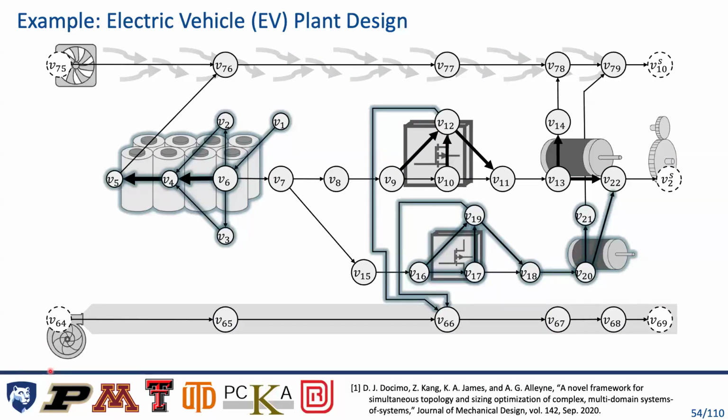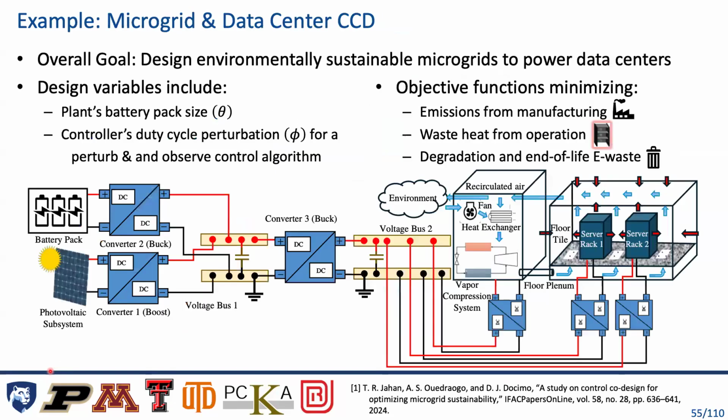We do want a second motor in this case, but it's used just minimally. So we don't need a large motor. We don't want to add in too much extra weight. And our power electronics, our inverters, our converters, all the power is being put through those things. So we probably want to dedicate liquid cooling for those components in specific in order to make sure that they don't heat up and have higher failure rates in the future.